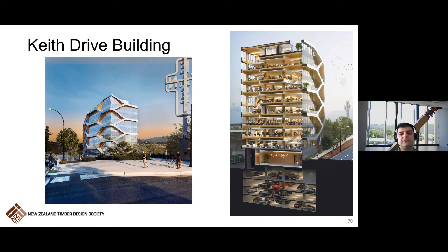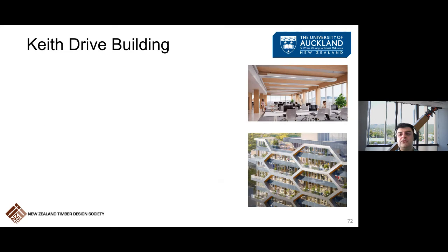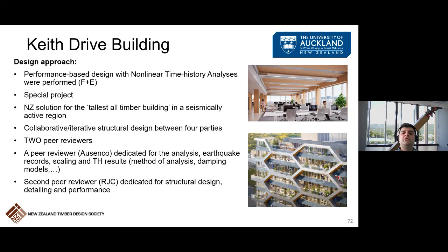This is a landmark project. It's the tallest all-timber project in a seismically active area. The lateral system is braces in one direction, and then a combination of braces and rocking walls in the other direction. So the design approach was a performance-based design. It was deemed a special project.